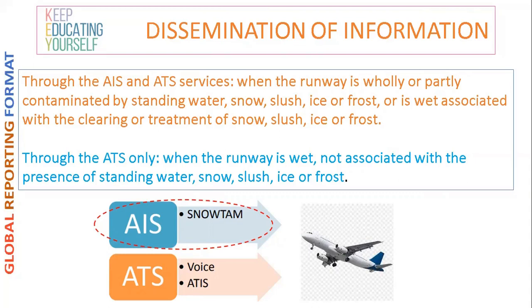So first I mentioned the runway condition code, contamination type, then change in reportable contaminant coverage percentage, and contaminant depth. Last but not least, if the pilot says your runway braking actions are not as good as reported, so whatever has been reported in your earlier runway condition report is not acceptable to the pilot as per his experience, you have to downgrade it. So this is the way where you have to go for a new runway condition report.